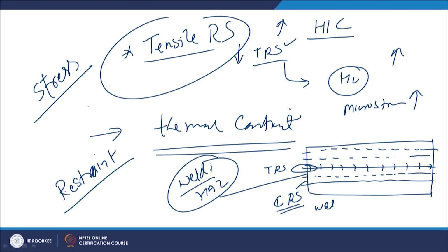Then the welding procedure also affects the residual stress being developed. The welding procedure includes preheating. Greater the amount of preheat, lower will be the residual stresses. Then the groove preparation or edge preparation will affect the weld area or the volume of the weld metal being deposited. In general, greater the weld metal volume, greater will be the residual stresses due to the increased magnitude of expansion and contraction. So, the residual stress magnitude in general increases with the increase of the weld area.